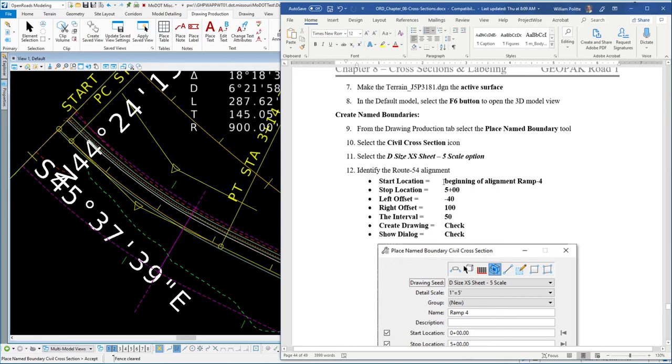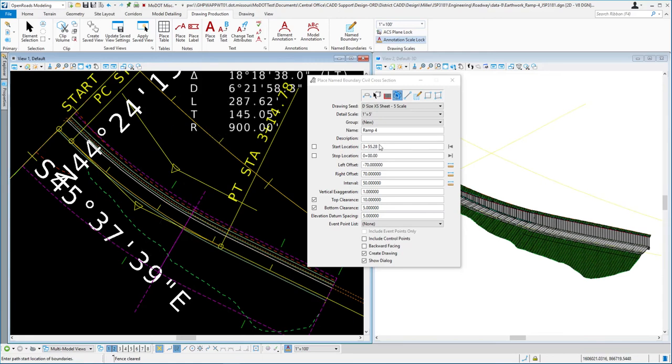Okay, so go back over into MicroStation. And the way I like to do it is start... you can do it many ways. You can come beyond the start location and just left click, or you can select in here and key in what you want, or you can hit this button off to the right that locks it to the start path. That would be good. Now you can see it's rubber banding off my cursor to apply the other stations.